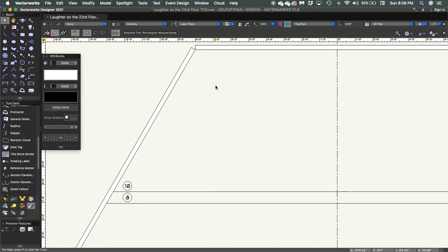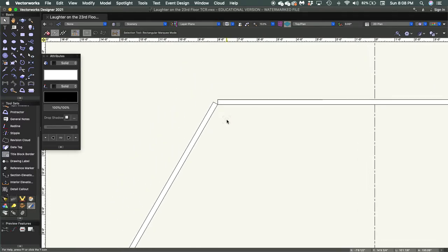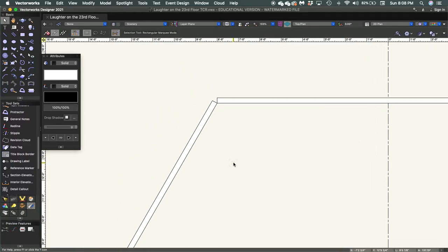I'm just going to zoom in here to where the stage right wall and the back wall intersect. And the first thing we're going to do is create a doorway. So I'm going to start by activating my rectangle, shortcut 4, and I'm going to start it right where these two meet. Drag that down to start, and like most of our rectangles, I'm going to tab into our floating display bar, and I'm going to make this one -6.5, so it's 6.5 inches thick, and tab over to the delta Y, and that's going to be -2 feet, 10 inches. Great, we'll click that to complete.